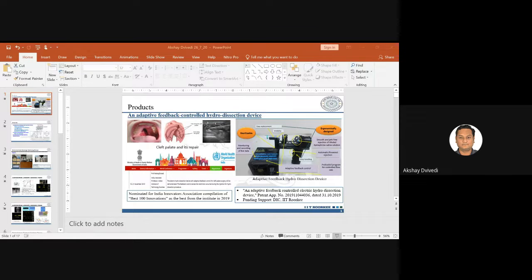So the process, which developed over a period of time, is now referred to as pressurized flow electrochemical discharge machining. If you look at the depth of a hole made by this process, it has reached around 2500 micrometers. In fact, it is double the previous value that we had. We have done substantial work on this, and it can even go beyond 5 millimeters now, no problem at all.